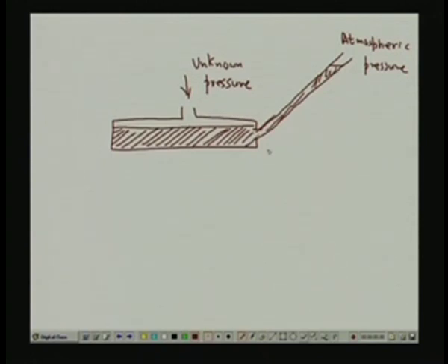Now, what is the difference between the inclined tube manometer and the well type manometer? You see, in the well type manometer this column is straight. Here, since the height is the same, the liquid has to travel a longer distance. So, ultimately, the advantage over the well type manometer is that the sensitivity in this case will be higher. So, I can measure a smaller pressure difference, and resolution will also be better, right. This is the advantage of this type of manometer. This is called the inclined tube manometer, or draft gauge.